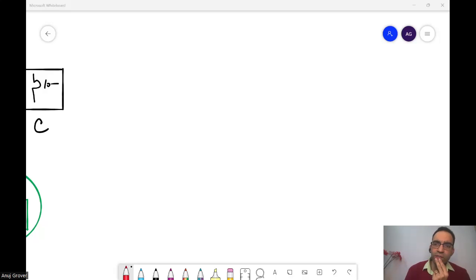Okay, if you have this capacitively coupled sense amplifier and you precharge it at a Q point, what is the Q point of a device, of a latch, let us say? Sir, VDD by 2? Depends on the sizing between NMOS and PMOS, but approximately VDD by 2. This is the place where my latch is maximally sensitive.